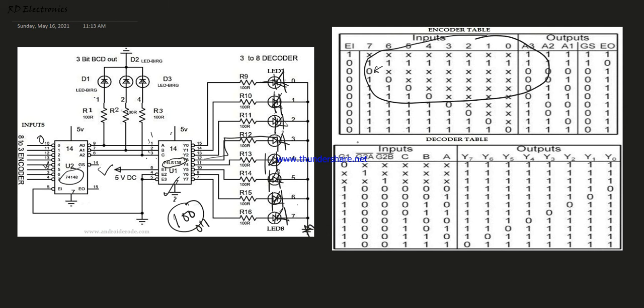And this is the normal decoder output, where three enable pins are available. When these enables are 100, then the IC is deactivated, and for 000 the output Y0 equals low. We already know that from 001 the output is Y1 and so on up to Y7. But note that when any enable input is not in its proper state, then the IC is not activated or enabled. It should be noted that the LEDs should be in reverse connection, otherwise it does not work properly. Here all LEDs are short circuited and connected to the plus VCC. I again repeat, this is the plus VCC point.